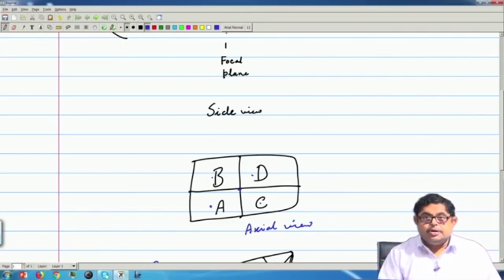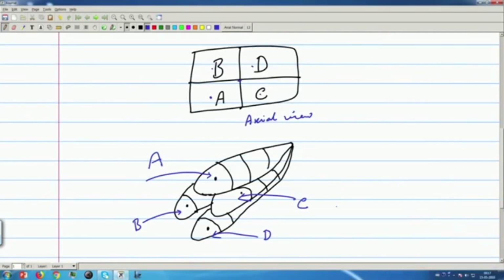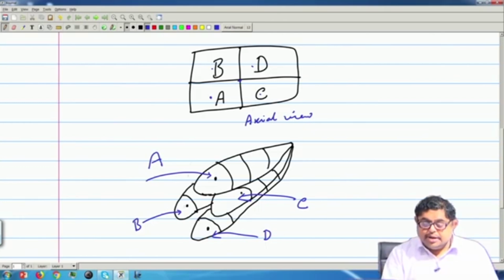Now, if these 4 horns are excited, they would form squint beams. The squint beams will be these. You see that the 4 feed horns produce these 4 squint beams. Due to these offsets, this squint comes, and you can note that the upper horns produce the lower beams, because of the squint. So, the upper horns are BD, producing BD here, and AC are the lower horns, producing AC here.